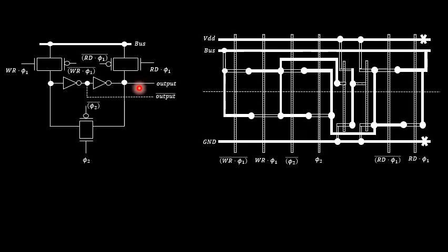I am making use of both PMOS as well as NMOS transistors. So here if you see, in the previous case it was only NMOS transistor for the write signal, phi 2 signal as well as read signal, but now it is cascading, that is a parallel combination of the PMOSFET as well as NMOSFET. So for all the NMOS transistors, you are supposed to draw a parallel connection of a PMOSFET. So three PMOSFETs are present over here, inverter 1 and inverter 2.